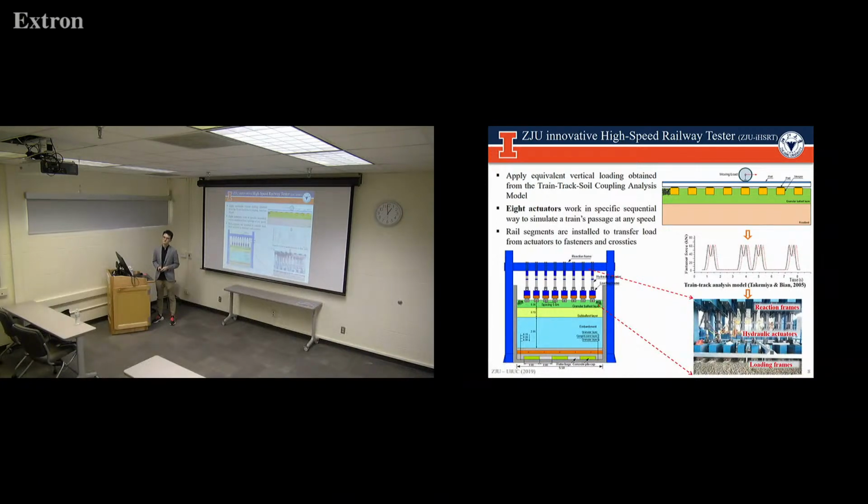What you're referring to is called an impact load. We know that happens a lot, according to the terrain as well as flat wheels. There are wheel impact load detectors, WILD for short, at many locations in the US railroad network. They're already established, and that's how they measure it.